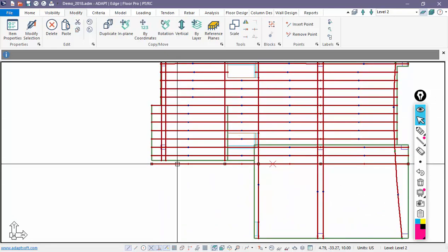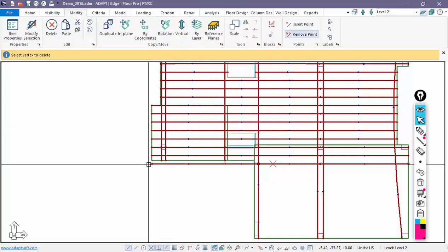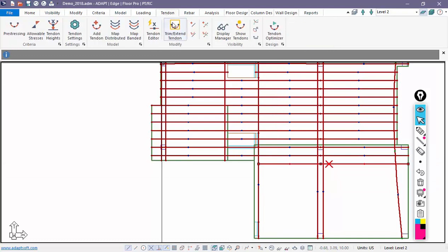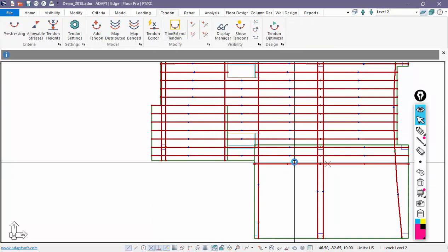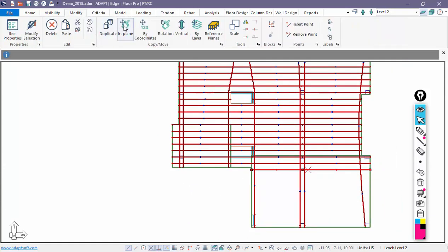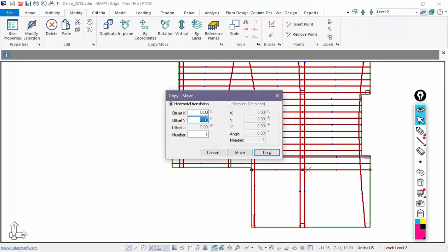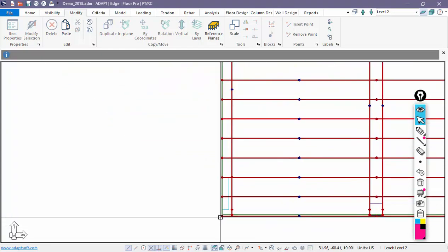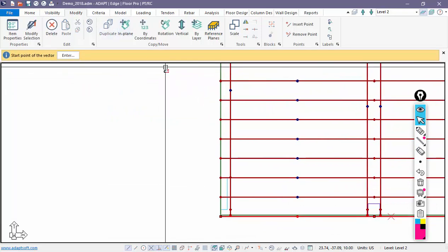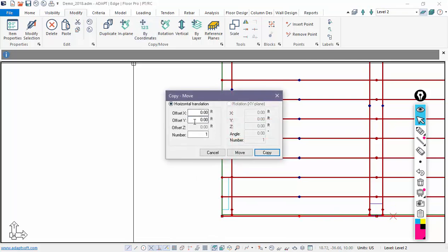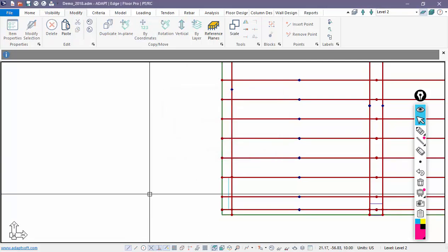And again, for this one, we'll right click, delete the vertices, and we'll take this and use trim extend again to push that out, and then we can copy this one down several times. So we'll copy that down 9 times. This will be a -3 foot distance, and copy. And I might want to move that inboard, so we'll take that and just move it. Select that tendon that falls outside of the slab and move it up, say by 1 foot, just say move.